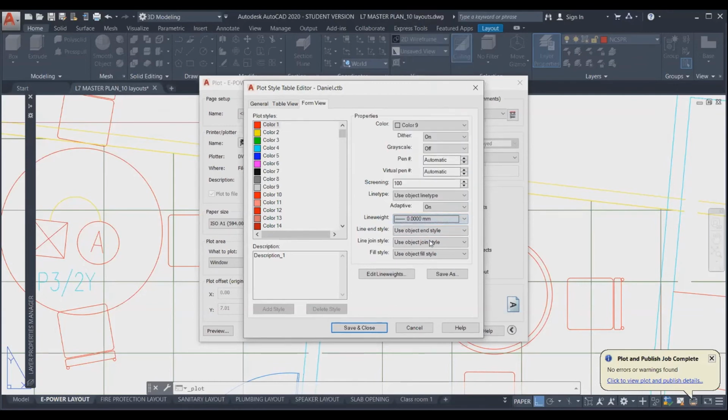So if you want, you can assign all the 255 colors. These 255 colors will be assigned by layer manager. If you assign in layer manager, it will reflect in your drawing. Then the drawing will go to pen assignment. Then pen assignment will assign your properties for a particular color, type, and width. It will reflect in your printing only. Otherwise, it will not reflect. But the color code is important to assign in your layer.